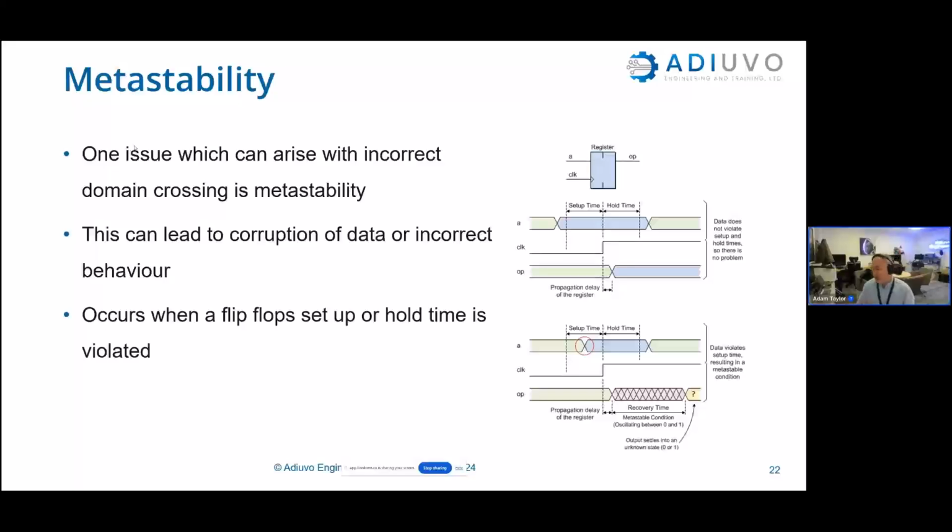And actually, I wrote a blog this week saying that even if things are synchronous, to remove clock uncertainty from the PLL, you might want to look at using the BUFG controls at really high clock frequencies to give you a little bit more margin when you try to achieve timing closure.